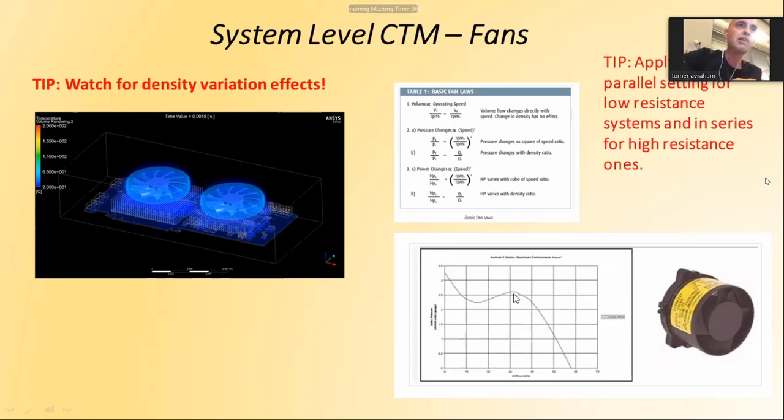So if this is for an F-16, then you have about 1/12 of the density, which means every cube has a lot fewer molecules of air, and the fan curve will go down here and will be something flat like this. So you need to think about altitude effects.